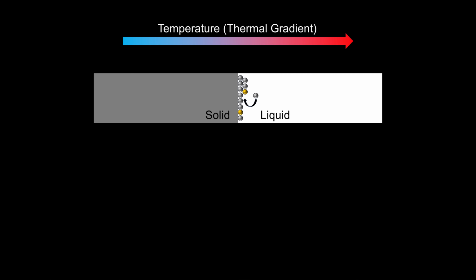applications in aircraft. To achieve the Columnar-to-Equiaxed transition, we need to know why columnar grains form in the first place and how to stop them. Let's consider what's happening at the atomic level during a solidifying or freezing metal. It's easiest to visualize this by imagining a two-dimensional system where the metal is solidifying from left to right with a flat interface, where the temperature increases moving away from the solid-liquid interface, which we call the thermal gradient.